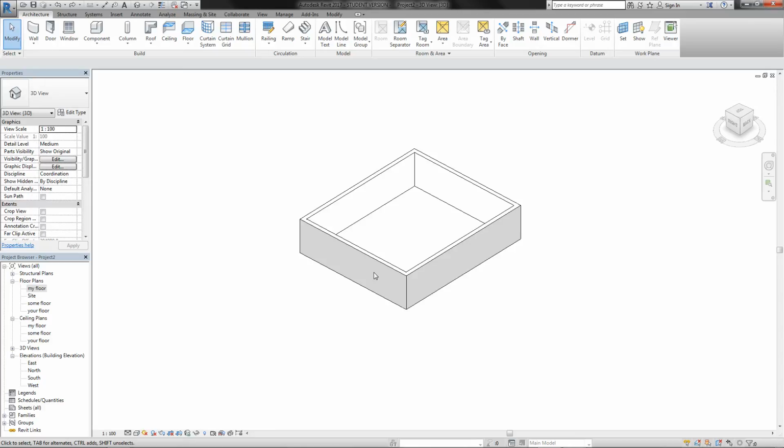Also, always have a folder for where your file is, say whatever building, and save your file in it. Each time you do a save, Revit will keep, I think, up to 40 saves by default for you. So let's say it's Maria's project, it will be Maria's project 0001, Maria's project 002. You'll get to 40 and then it will override those. So by default, you'll get some versioning system in it, but it's good to have your own as well. So if you open your folder and see there are tons of different files there, don't freak out, that's what Revit does.